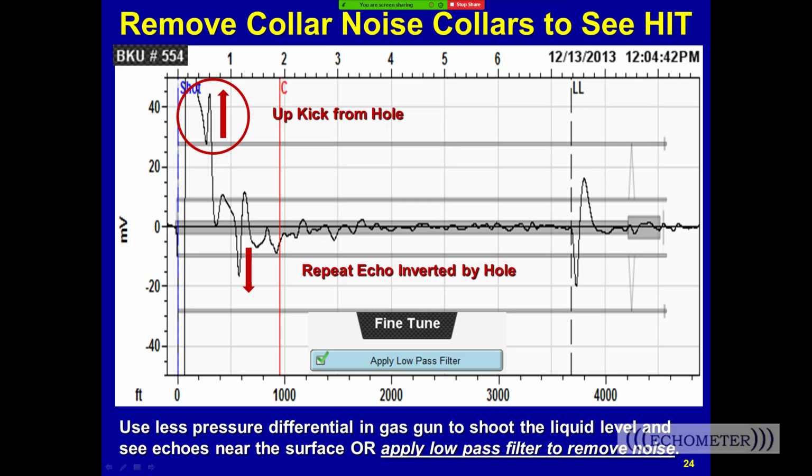So I'd say yes, if you're shooting down the tubing on a gas lift well or a plunger lift well or a gas well, it's common to shoot down the tubing and you get an accurate static bottomhole pressure. The assumption of the software is the liquid in the tubing is based on the production rate. So if it's 10% oil and 90% water, and you have liquid above the end of the tubing, we're going to divide the gradient based on the production.